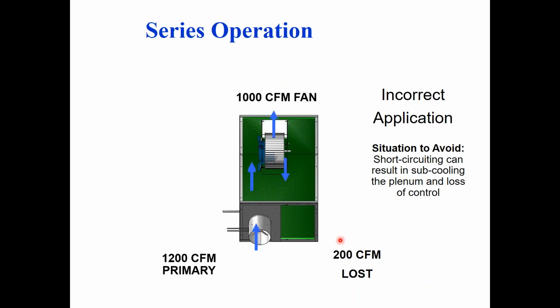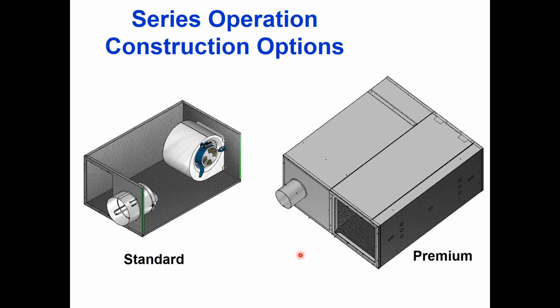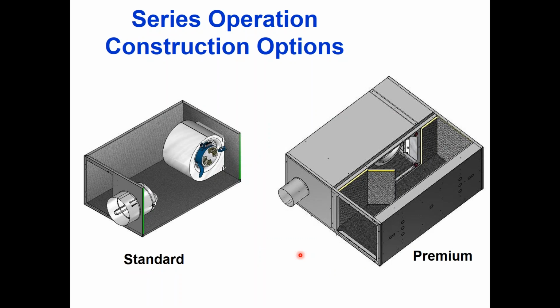By the way, when we balance these, I'm not an air balancer, but I used to do building automation controls, so I would have to go to every job site with the air balancer. The way we balance these typically is we put a piece of toilet paper on a stick and hold it up here at the inlet and see if it sucks in or if it blows out. And then we keep dialing the fan up or down until we get the toilet paper to hang there evenly, meaning that it's equalized between the two. It's super scientific.